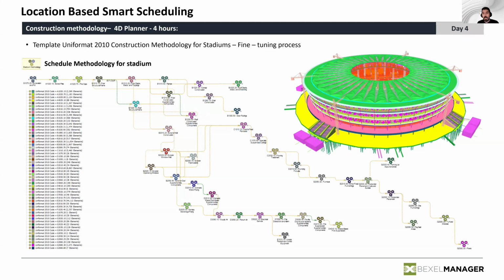Then the next step was, okay, we did the location part. So we actually located all the model elements within functional zones that will be the broad structure of our schedule. The next step was the functional structure of our schedule, or let's say the methodology or sequence of execution. So we had to specify in which way this building is going to be built.